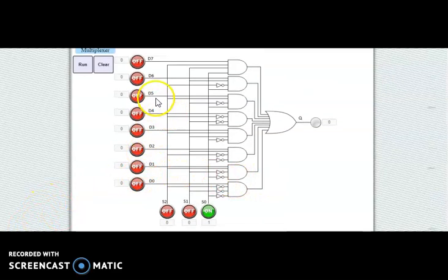But a multiplexer can be built for any number, like 2:1, 4:1, 8:1, 16:1, 32:1. So how are we going to do that? By the number of AND gates. If 16:1, there are 16 AND gates and 1 OR gate. How many select inputs? 4 select inputs. That is how the ratio of inputs to select inputs has been decided: 2 power n inputs, n select inputs and 1 output.